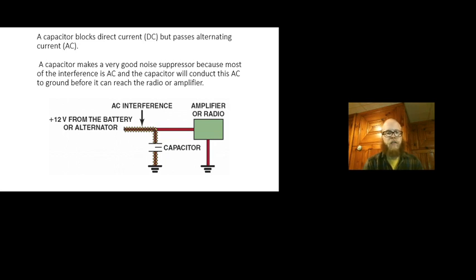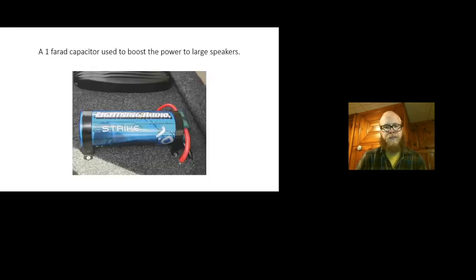Also, sometimes these capacitors are used because the amount of current that's caused by an ignition coil firing could interfere with some of our sensors since there's not that much current flowing through those wires. So they're oftentimes just there to try to keep everything as clean as possible so we don't get any weird interference causing issues with radios or with sensing circuits.